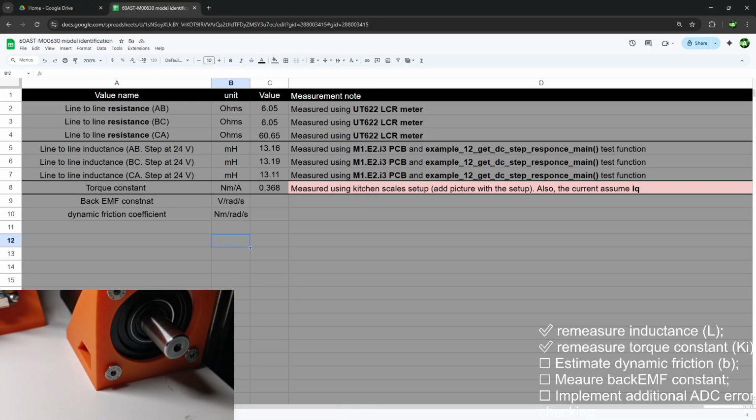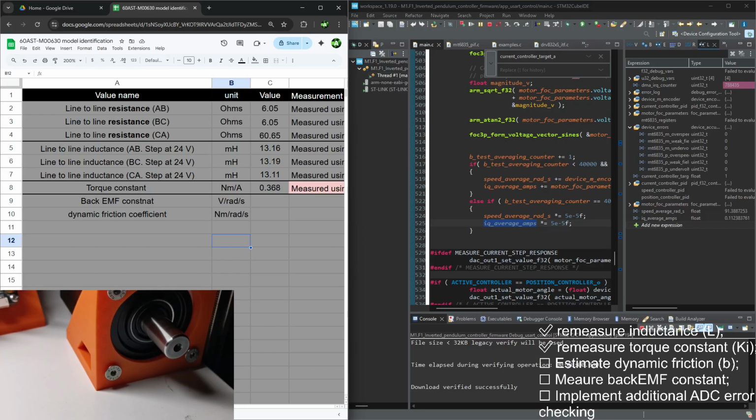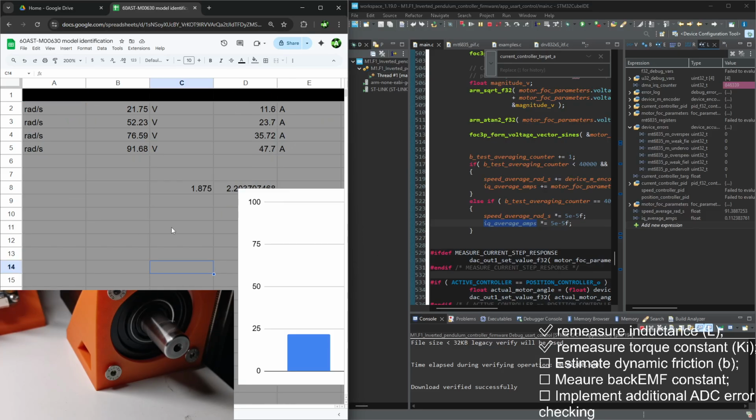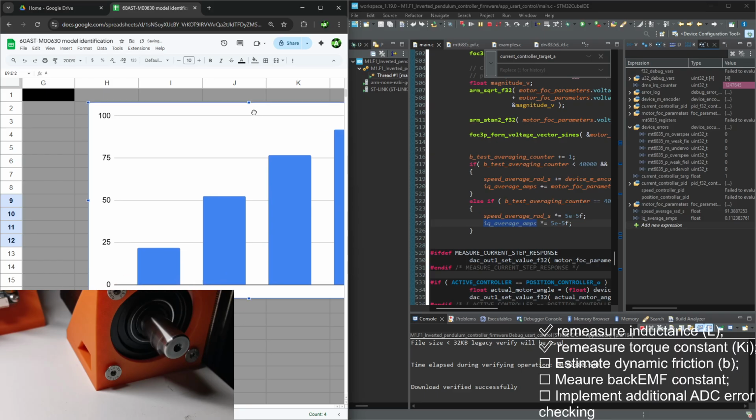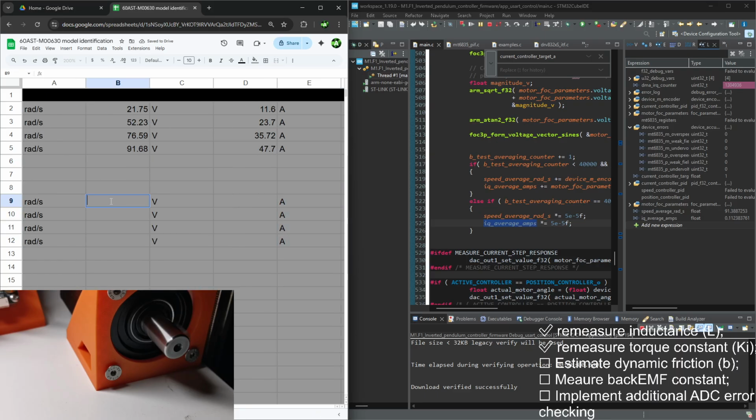So let me put them on a separate page, which is here. Okay, this was our first investigation that came to the conclusion that we have encoder problems. Now let's add another investigation, of course, our volts and our amps. We will also need to measure the voltage, which is absolutely fine. First we have our 48 volts expected. We will measure it.